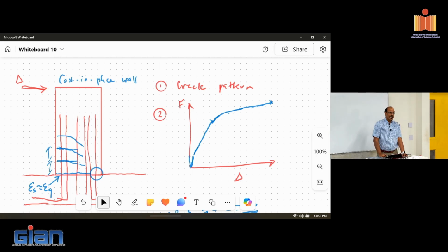Right? So that's a cast in place. So think of this as what typically the behavior will be at the bottom of a column, at the bottom of a wall as we are looking at it, and then you could also look at a beam forming moment resistance against the face of the column as we discussed yesterday.